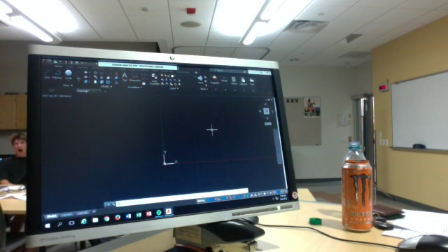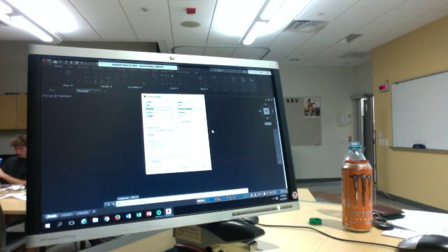Drawing units. It's one of those things that I was saying earlier, one of the rather important things when you're working on civil versus architectural or mechanical drawings. In order to use the drawing units, it's real simple. You just type in units and hit enter. So you get the drawing unit dialog box pop up. We're going to go over that a little bit more later.